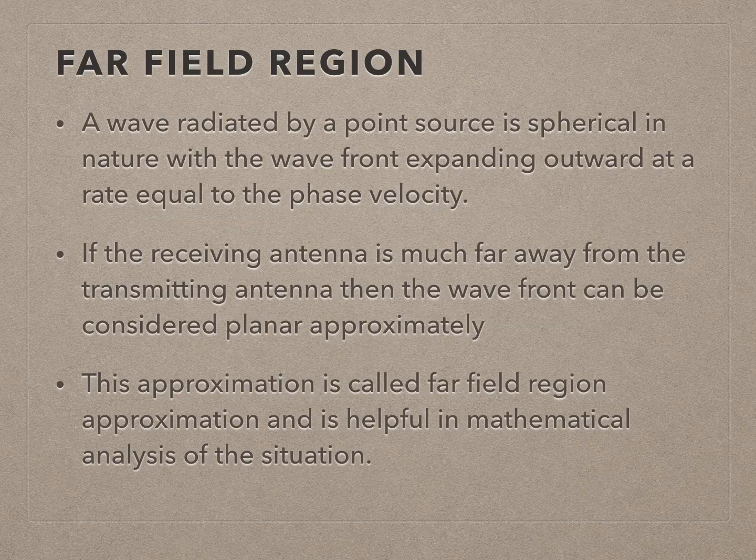Far field region. A wave radiated by a point source is spherical in nature, with the wave front expanding outward at a rate equal to the phase velocity. If the receiving antenna is much farther away from the transmitting antenna, then the wave front can be considered approximately planar. This approximation is called the far field region approximation and is helpful in mathematical simplification of the situation.